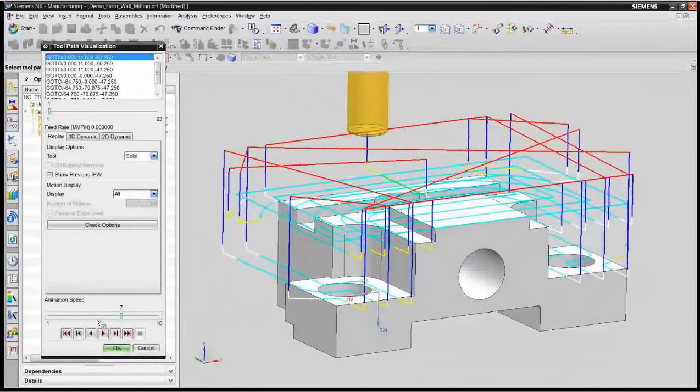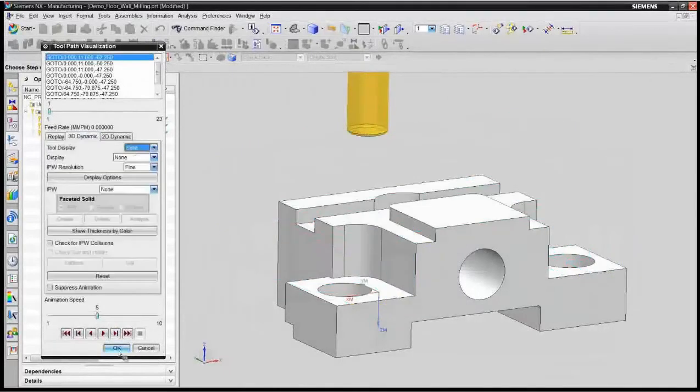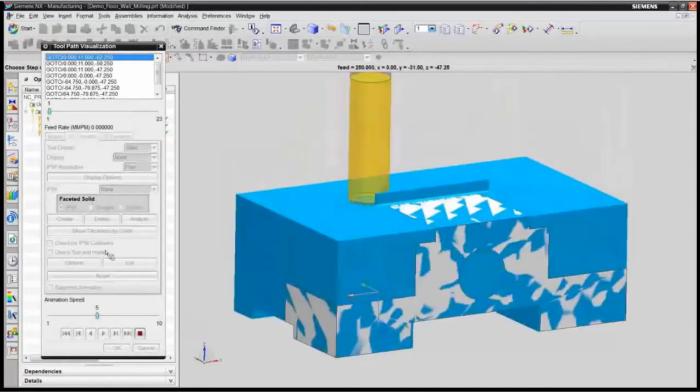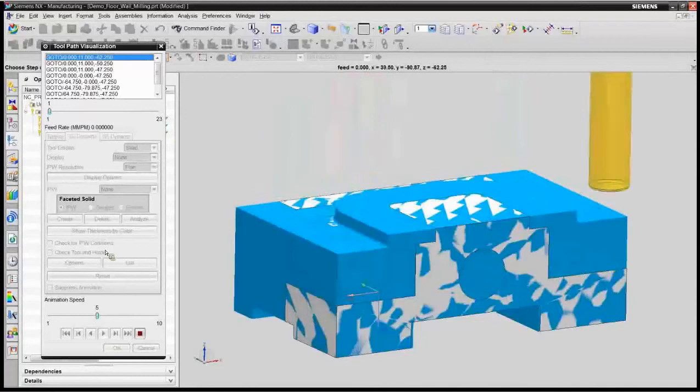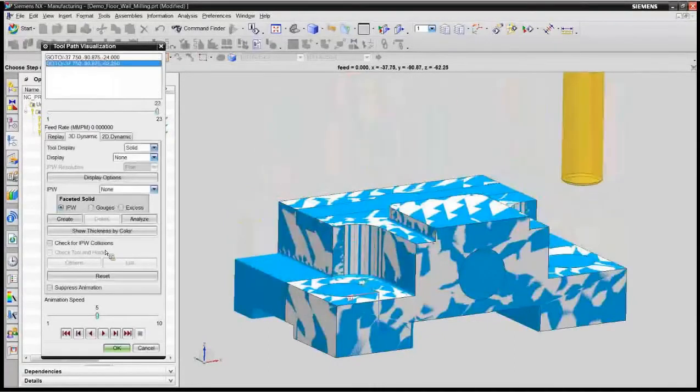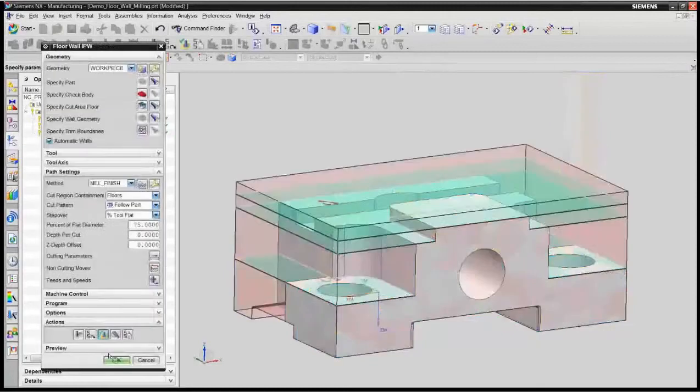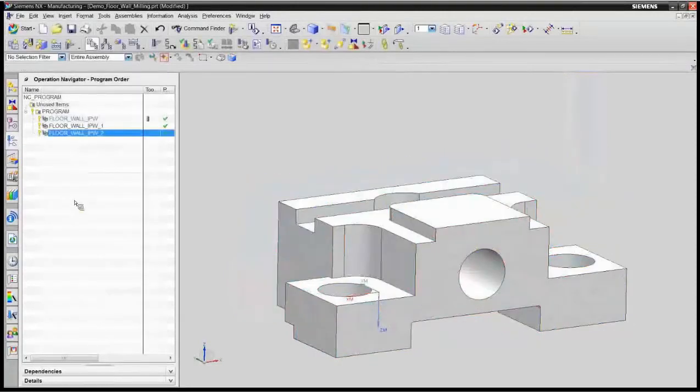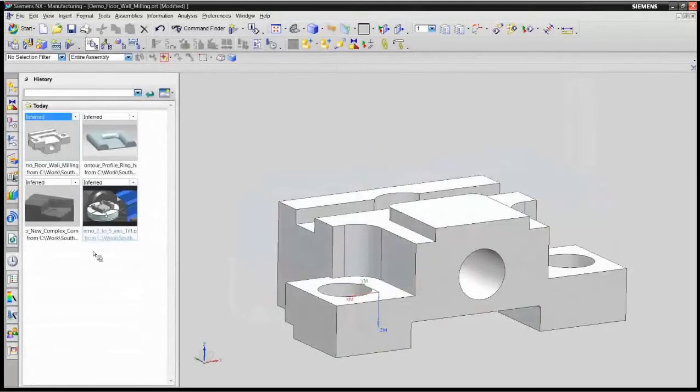So very quickly and easily you can create these volumetric tool passes. This is introduced to help with the creation of tool paths on 2.5D, so you're not actually doing 3-axis machining on these type of tool paths. Okay? And like I said, there is a separate video out there with tech tips just on these type of operations, and I invite you to go out and review that.